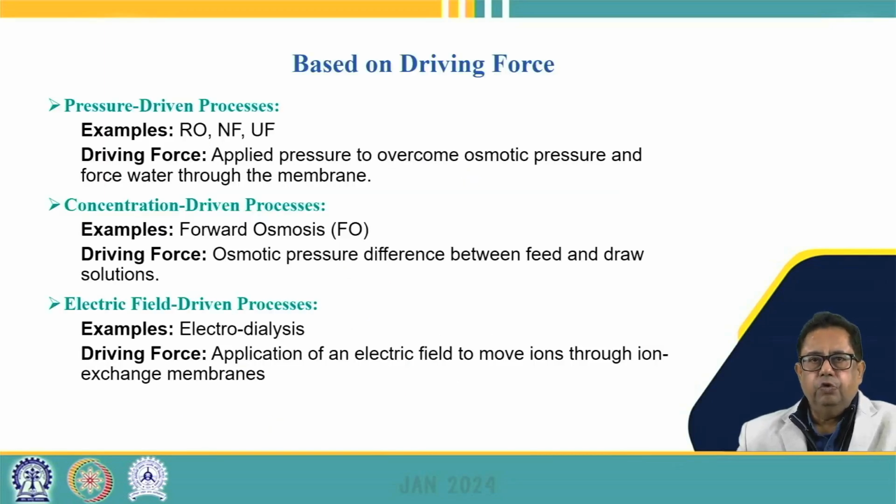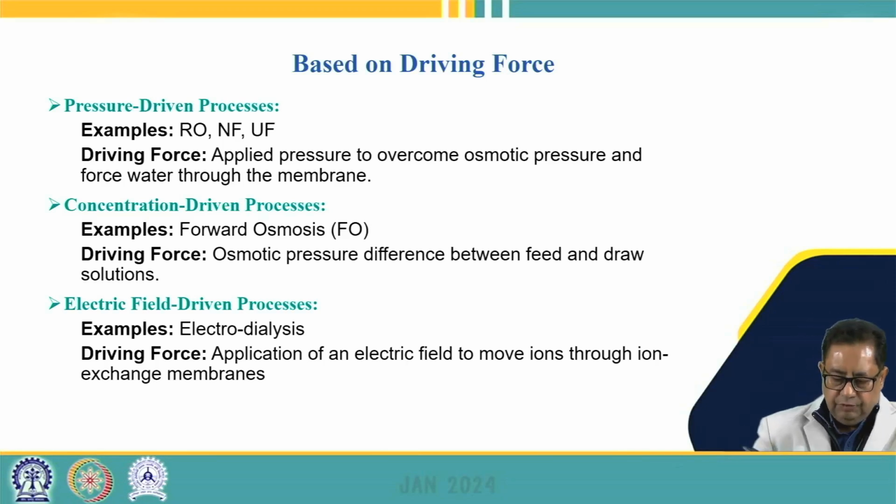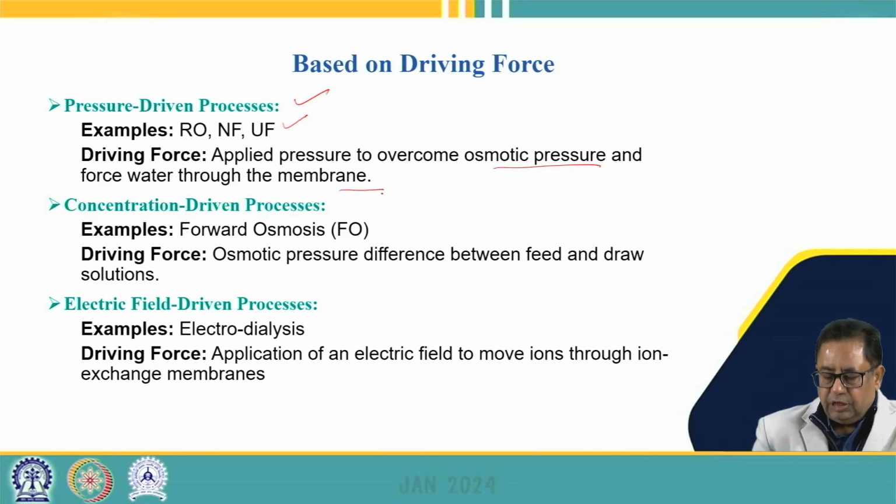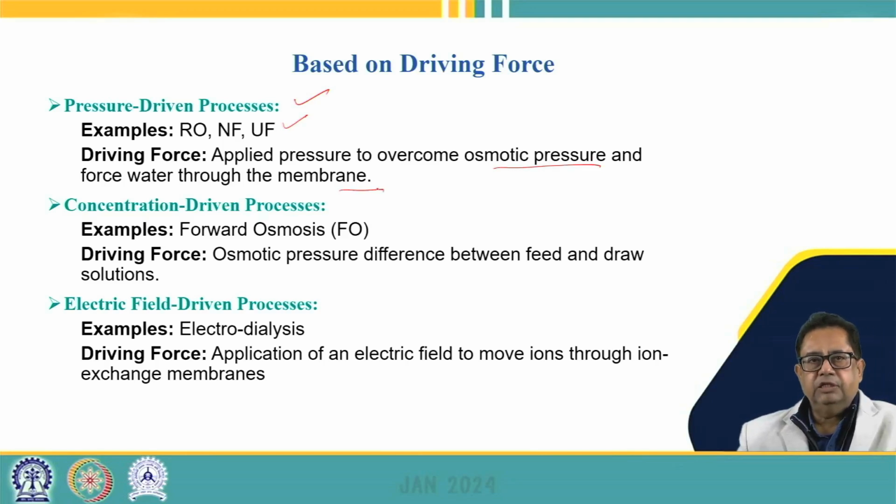Similarly, the driving force can also classify the membrane processes, where we can have the pressure driven processes, where we talk about the RO, nanofiltration, ultrafiltration. So we have to apply a very high pressure so that we can overcome the osmotic pressure, and the water can be forced through the membranes as the pore size is very small.